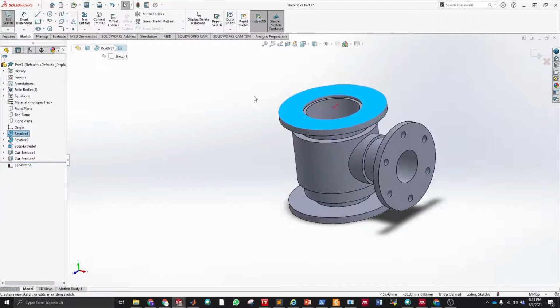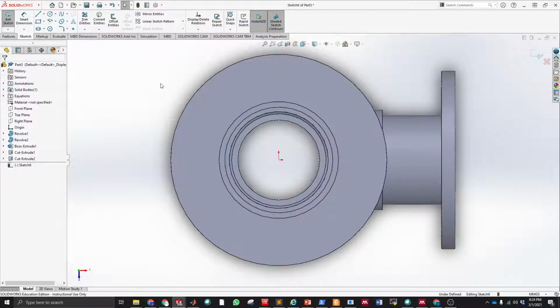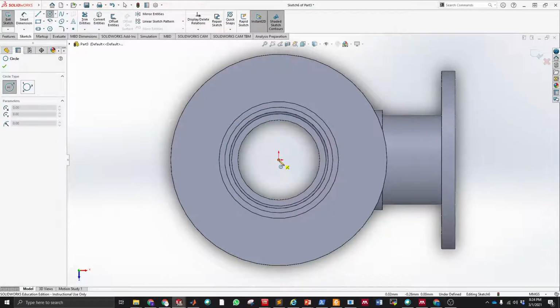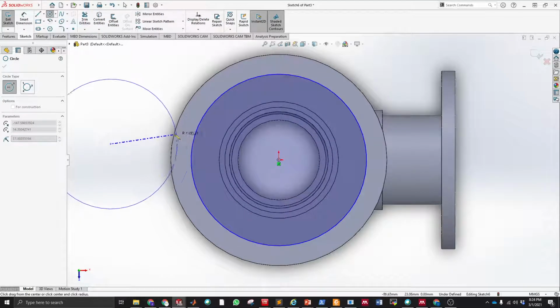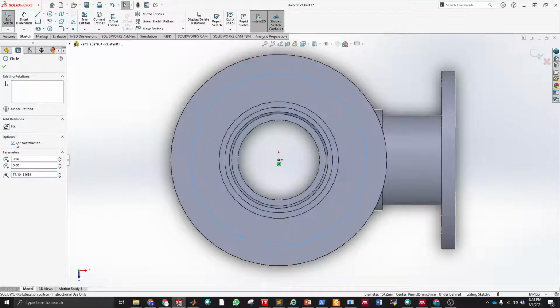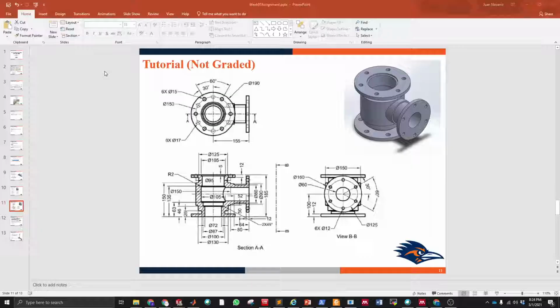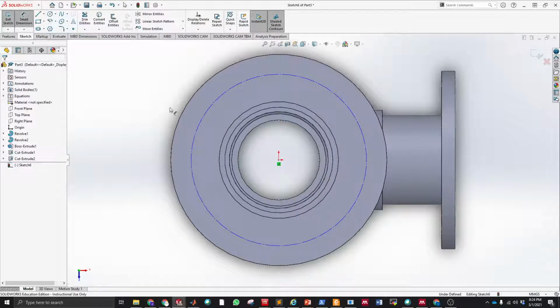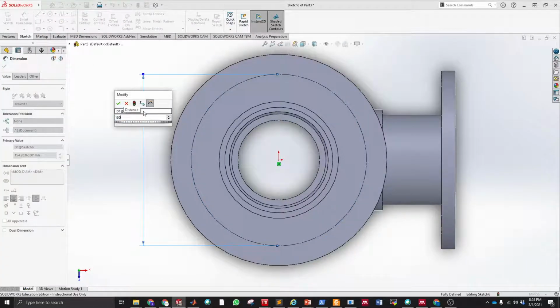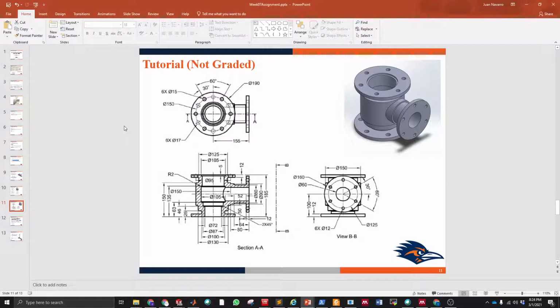Here in the top, I'm gonna select create a sketch, Control 8. Same thing, pretty much. This circle is for construction. The diameter of that circle is 150. And then we have that the circle this time is aligned to the line on the right. So I'm going to start with this circle here of diameter 15.